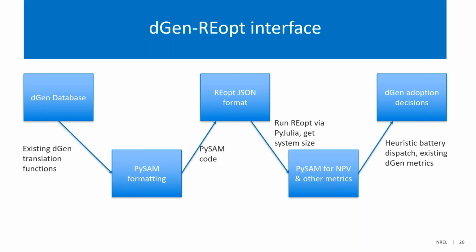There's a new function within PySAM that we released with version 4.2 that allows users to get back a JSON object that works for the PV plus battery optimization that we're trying to do here. The previous one, you would assign just the battery. This one configures the REopt call correctly to do both.